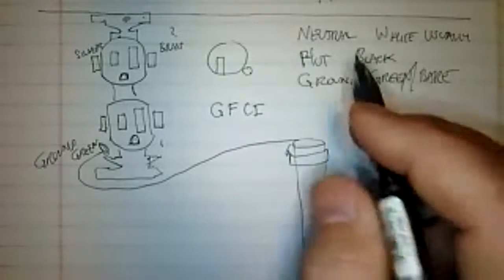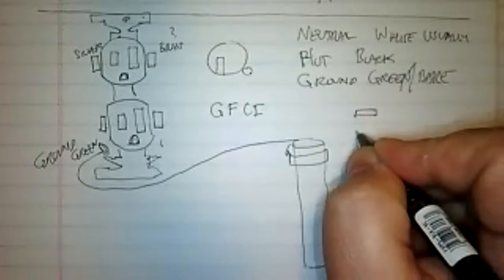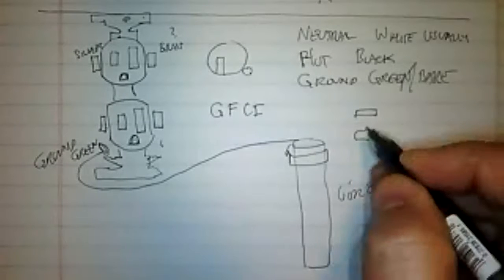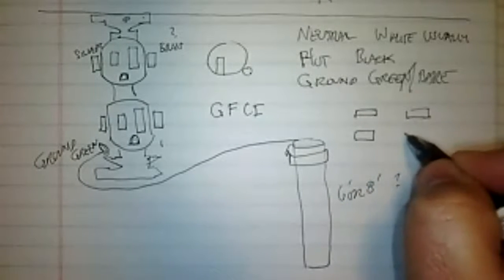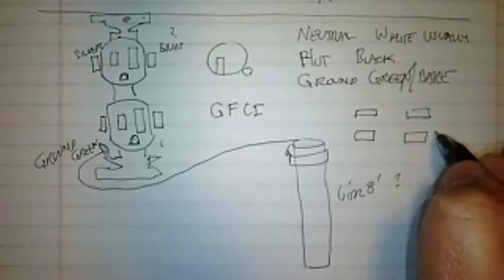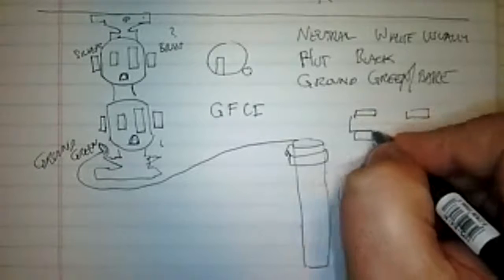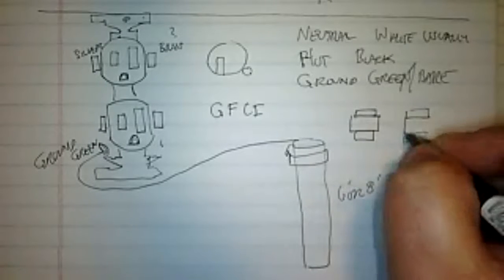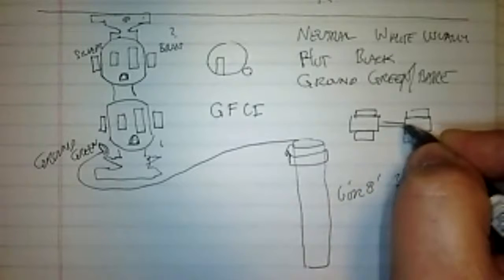We also have older houses that will have fuses, and what that means is there's a copper ending for a wire that runs to a power supply, say the telephone pole, and there's a copper ending that runs to all the receptacles in your house, or all the receptacles on that leg. And then you put a fuse in there, which is basically just a little ribbon of metal.